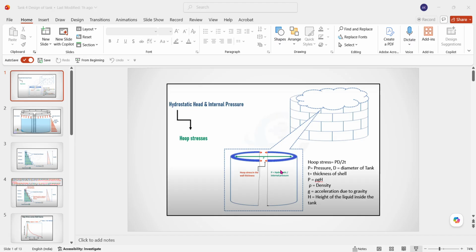It is noticed that stress will be maximum at 1 foot or 305 millimeter above the bottom plate, where the shell will behave like a free cylindrical shell. The stress will be maximum here, and that will govern for finding out the shell thickness.